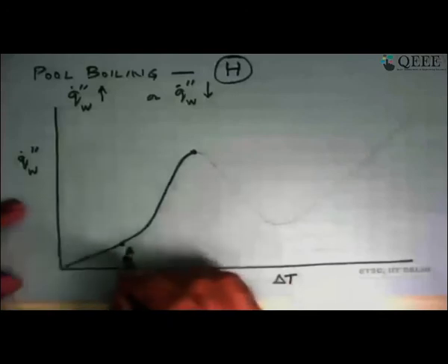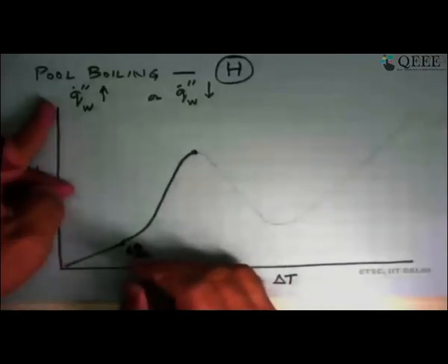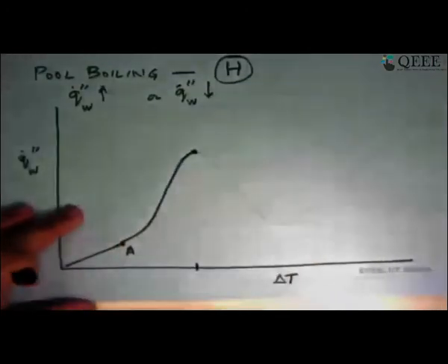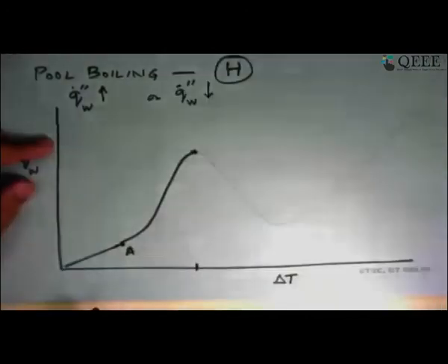Then this curve was the nucleate boiling curve. And we are electrically heating it. So we are going steadily up along this path. So we got here and the delta T became this much. Now if you increase Q dot a little bit, the surface is already blanketed by vapor.